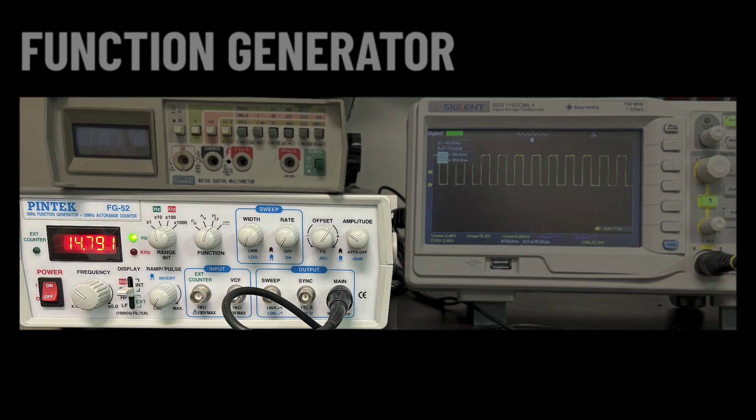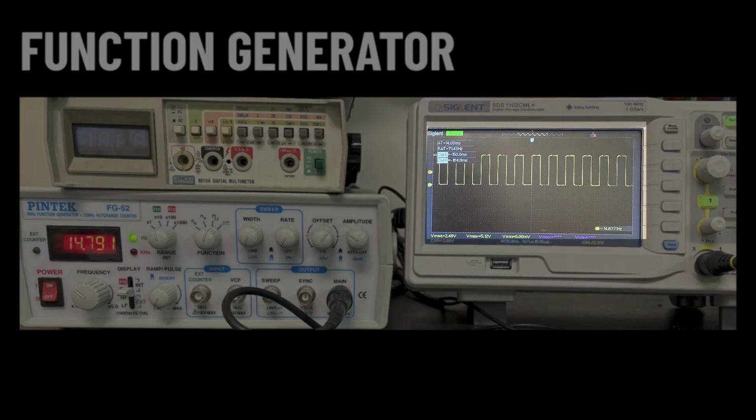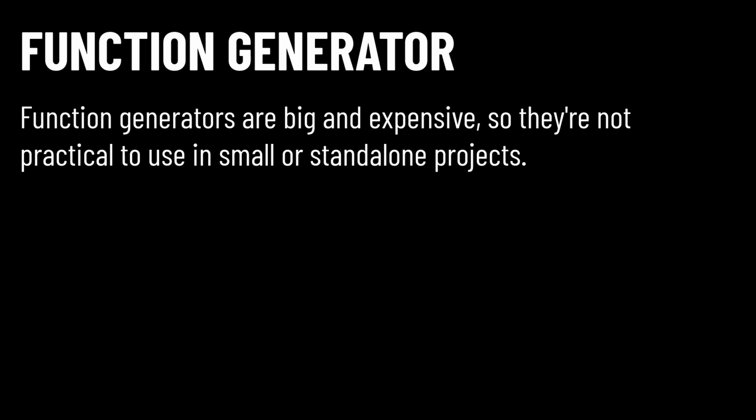The first is a function generator. A function generator can generate multiple different voltage signals that can change with respect to time. Function generators typically have an output signal that generates a TTL clock signal, which is a square wave oscillating between 0 and 5 volts. There's not much to take into consideration when using a function generator, other than it's large and expensive. If you're building a circuit that requires a clock signal, and you want it to be small enough to fit on a single breadboard, then a function generator may not be an appropriate clock source.